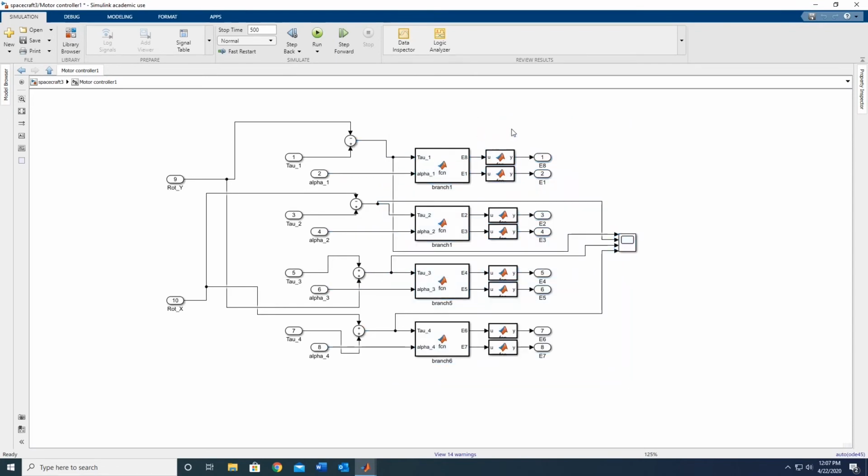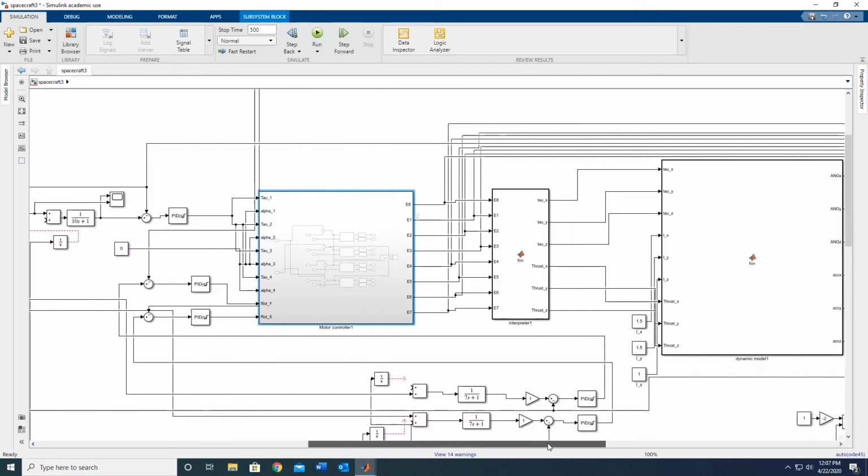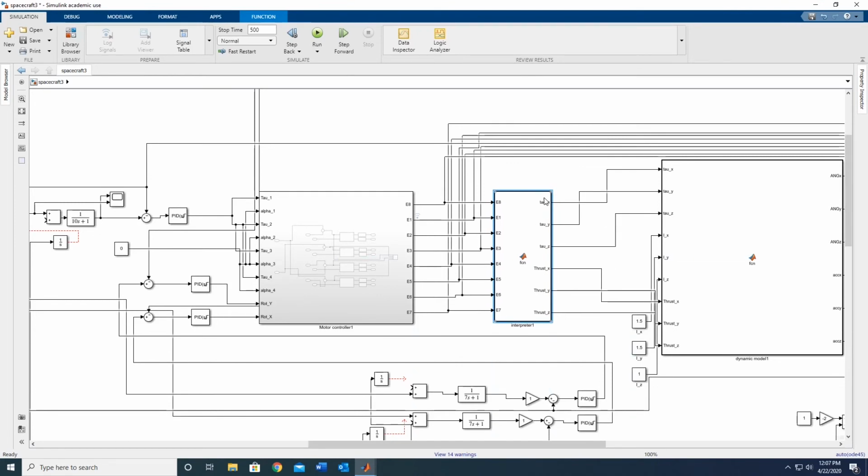Okay. Then when I've processed that data, I feed it into another block which computes the individual actuator inputs. This is engine 1 through 8, so this is the thrust level in each of the engines. It converts those into a thrust and torque about the vehicle in the vehicle's home coordinate system. One of the concepts you'll get very familiar with if you study guidance, navigation, and control is the idea of coordinate frame stitching.